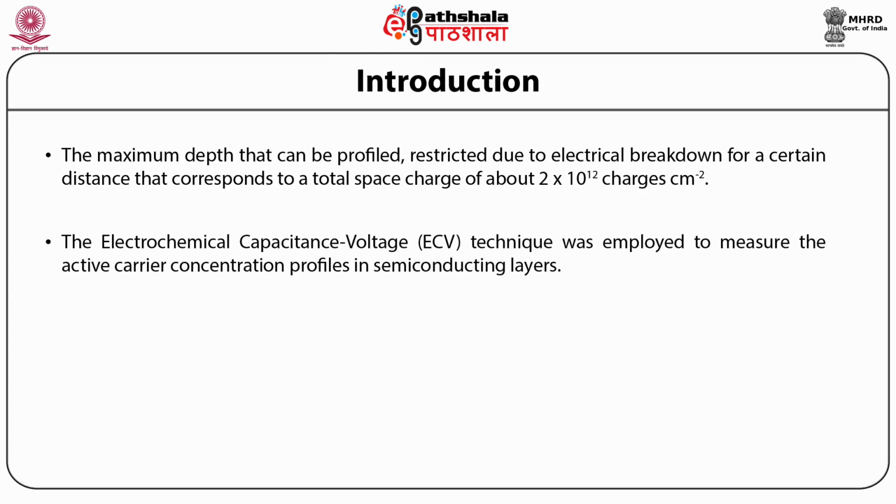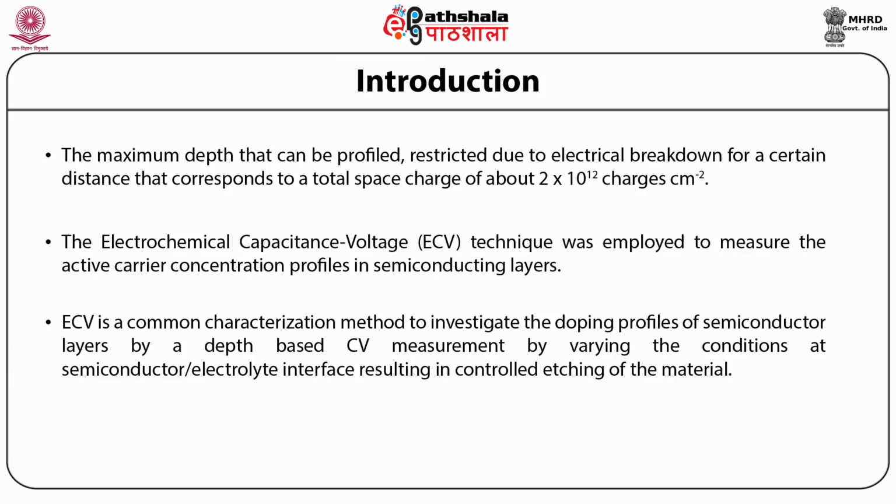The electrochemical capacitance voltage technique was employed to measure the active carrier concentration profiles in semiconducting layers. ECV is a common characterization method to investigate the doping profiles of semiconductor layers by a depth-based CV measurement, by varying the conditions at the semiconductor electrode interface, resulting in controlled etching of the material.